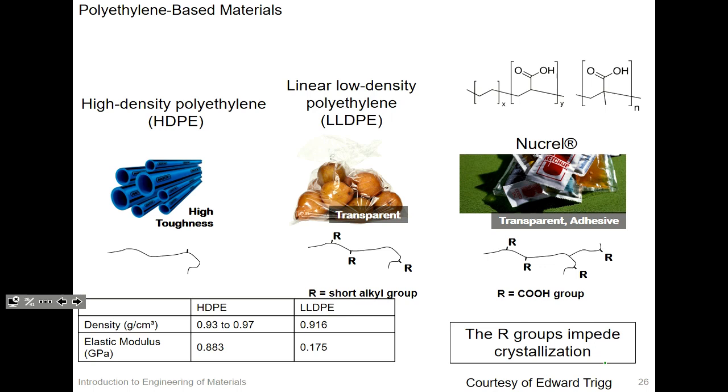And all within, let's say, even the same family. So with polyethylene, if you have linear chains, what we talked about before was something that looks like this. Okay, so this is 2 mers of polyethylene. The hydrogen atoms are going off of the page. I'm going to put square brackets around the repeat unit just to remind you what polyethylene looks like. So that's 2 mers of polyethylene. If I were to continue that, you could imagine,